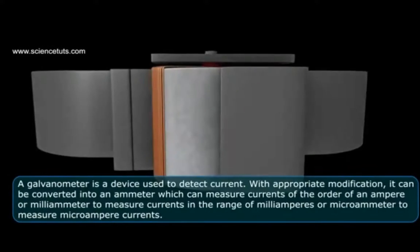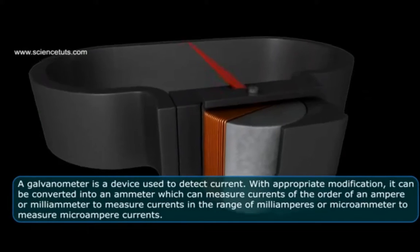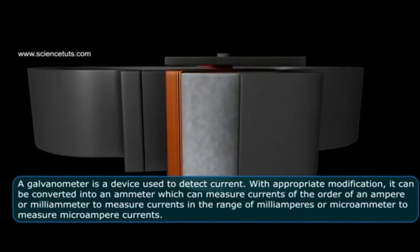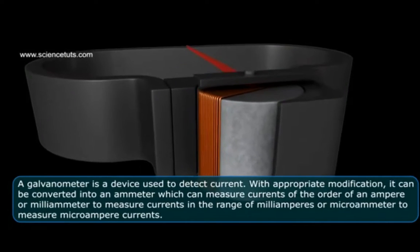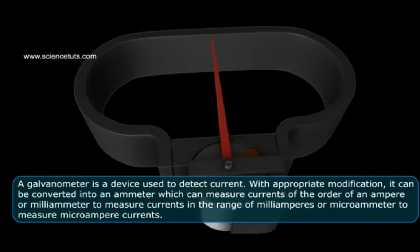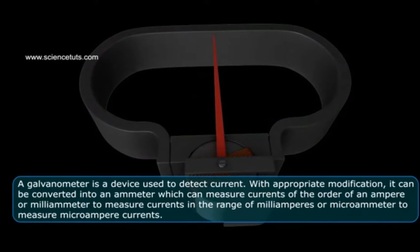Galvanometer. A galvanometer is a device used to detect current. With appropriate modification, it can be converted into an ammeter, which can measure currents of the order of an ampere, or a milliammeter to measure currents in the range of milliamperes, or a microammeter to measure microamp currents.